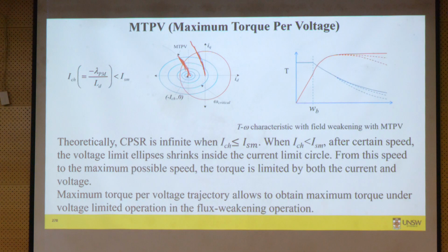Okay, so the motor with very deep flux weakening, IPMSM, so they operate first in MTPA up to base speed, then they operate with flux weakening here, and after that, once they see the MTPP trajectory, they will operate along the MTPP trajectory. Okay, and for MTPP again there is another way of calculating negative ID current. So it all becomes how to calculate that negative ID current, okay, in IPMSM for all these controls.